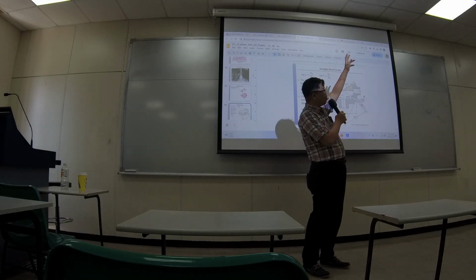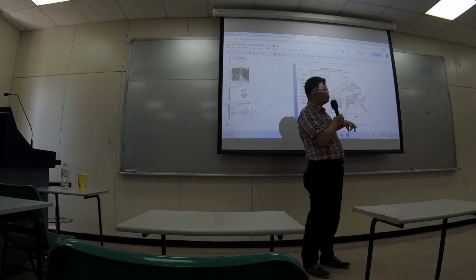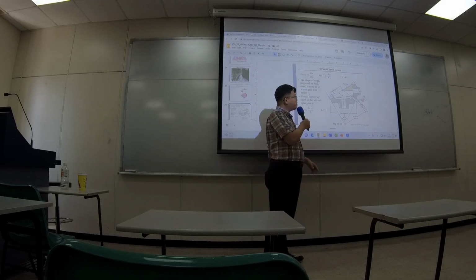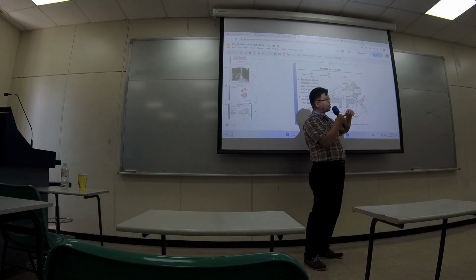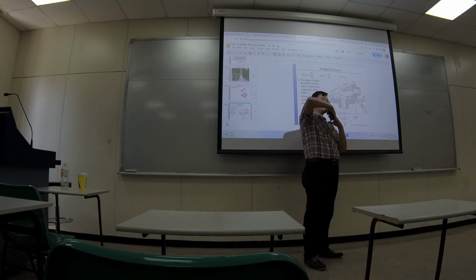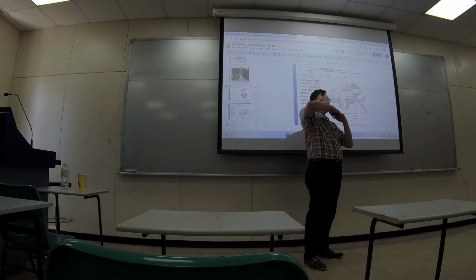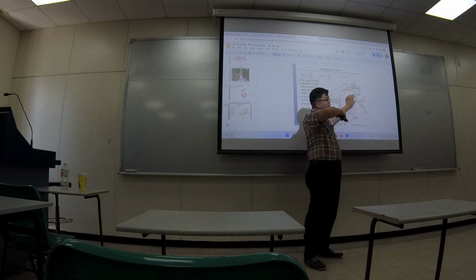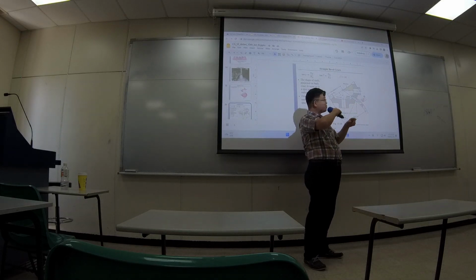It's very difficult for us to take something from the previous slides and then use it to study whatever is happening for the bevel gears. People figure out a way. When two bevel gears connect with each other, they still have similar conjugate motion, and the profile still looks a little bit like the spur gear. So they treat the local area right here just like spur gears, the circle ones.